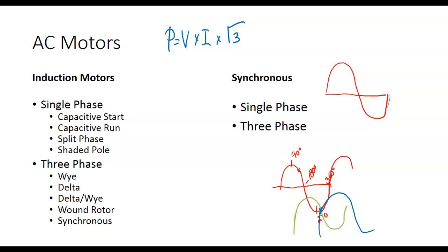And so if you've got an AC motor that just hums at you when you put power on it, there's a high probability that you've lost the component that causes the phase shift. So you can buy a new motor for $200 or $300, or you can buy a start capacitor for about $20. But it's going to hum at you, right? If you can take the motor, you don't want to do this on something that's going to hurt you.